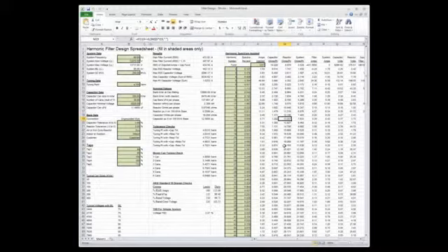Now, one of the things about harmonic filters that you don't have to have a real concern for is what's called back-to-back switching. Often if you have two capacitor banks located near each other, you have to include some type of surge protection, a reactor in the circuit, so that when you hook one up to the other, it doesn't dump all of its energy in and basically cause a problem. For back-to-back switching, the reactors in the filters themselves help you.